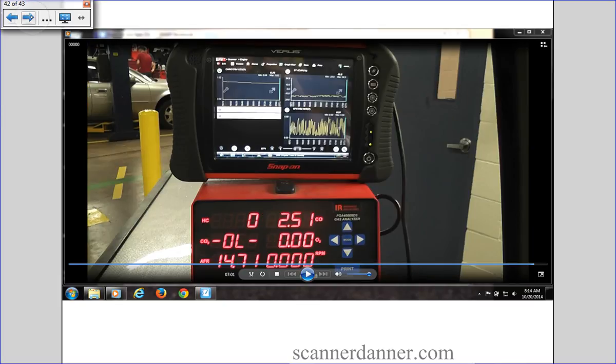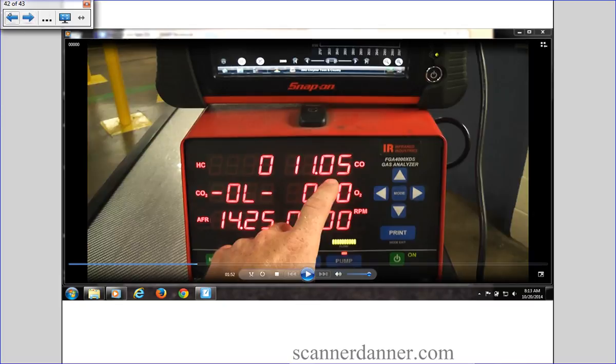And that's it with this one, guys, just so you're comfortable. Why this didn't make it, I'll show you in the next image. During the fixed lean O2 condition, what do we see the tailpipe CO percentage at? 11%. So is the sensor lying? Yes, it is. It's a dead sensor. Check the powers and grounds, same routine.